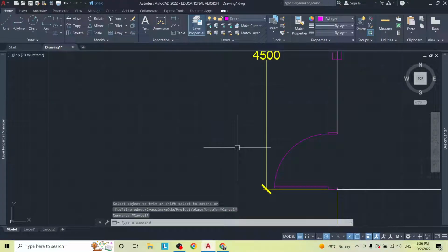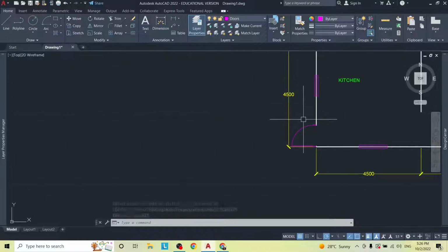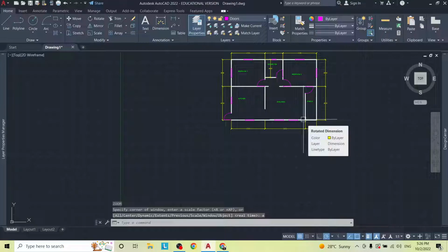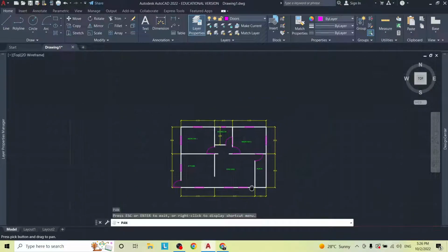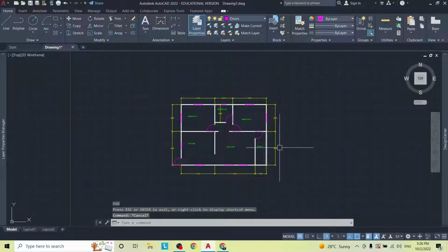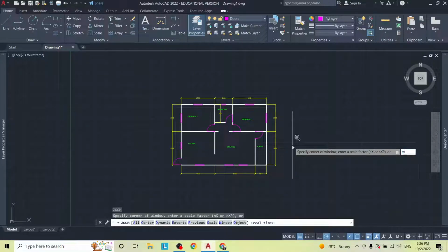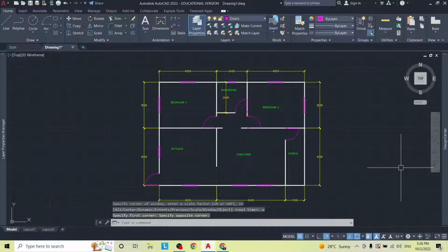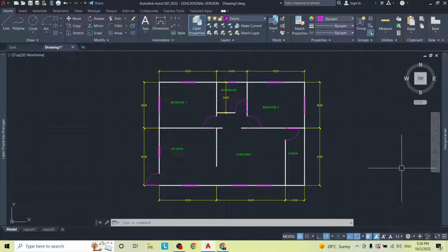All right, next up, I believe that's it. Let me just zoom into this area and center this drawing a bit. Zoom, W for window, draw the window around it. Right, so we can see we have the sketch in AutoCAD that we would be using to produce our floor plans and our order plans.